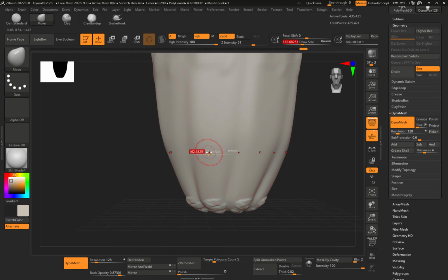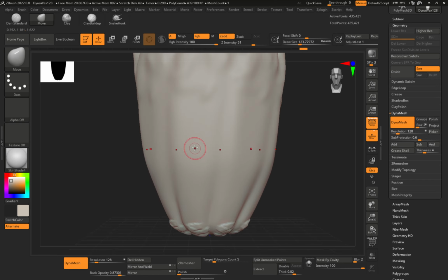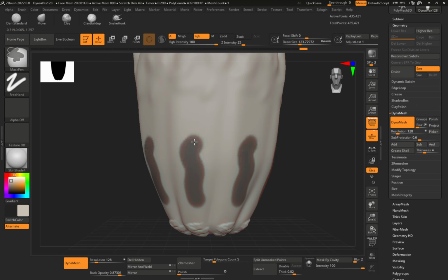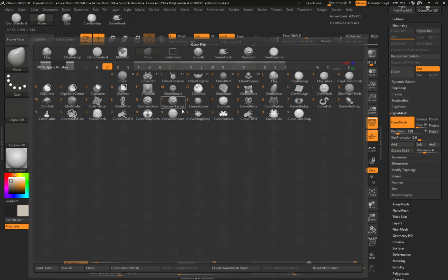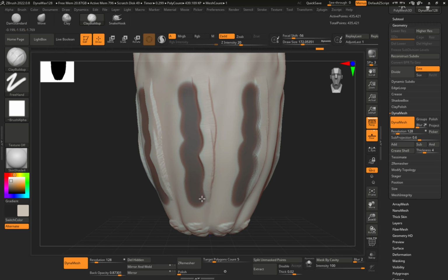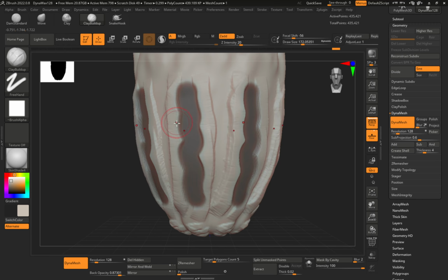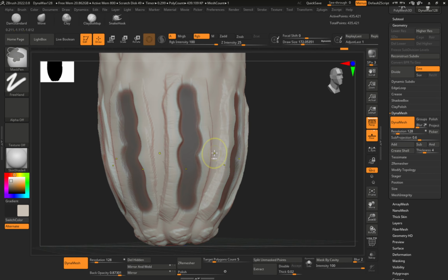The last thing I'm going to cover is the masking tool and how to save your ZBrush file. So the mask tool, if you hold down Control, it turns yellow. You'll see your cursor turns yellow, and over here you'll see your brush becomes a mask pen brush. So if you hold down Control, you can draw a mask out, right? And what the mask does is, wrong brush here, use Clay Buildup. If you sculpt around it, you're not going to be able to sculpt on the mask, right?